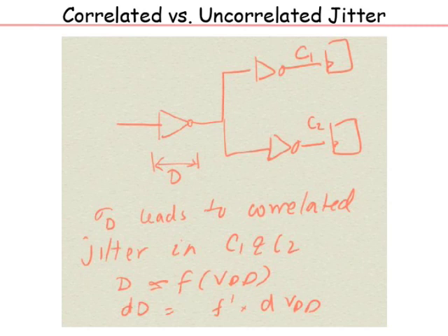Also you have substrate noise, which I have kind of ignored, but any fluctuation in the substrate potential will also cause a change in the threshold voltage, and so a change in the delay. Then coupling: remember we discussed aggressors and victims. If signals are going in the same direction, the effective capacitance is less.